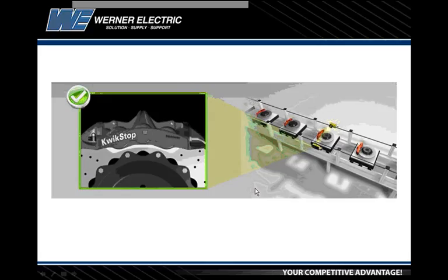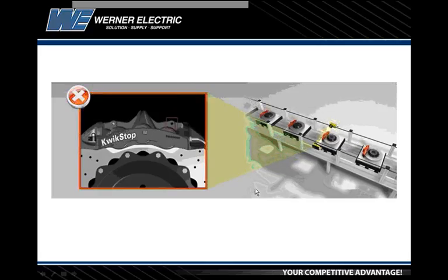Okay, this is a little different one. It's hard to see the defect, but these cameras are checking for the presence or absence of a rivet in the top of the caliper housing. So on this image on the right side of the caliper housing, there's a rivet missing. And traditionally we might have solved an application like this with a photo eye. If there's only two items that you want to check, it's possible that a photo eye would make more sense than a vision system.